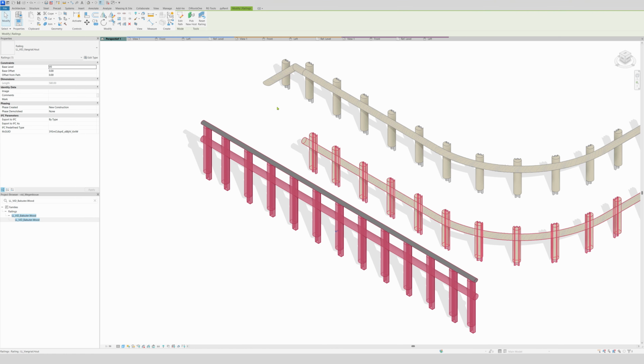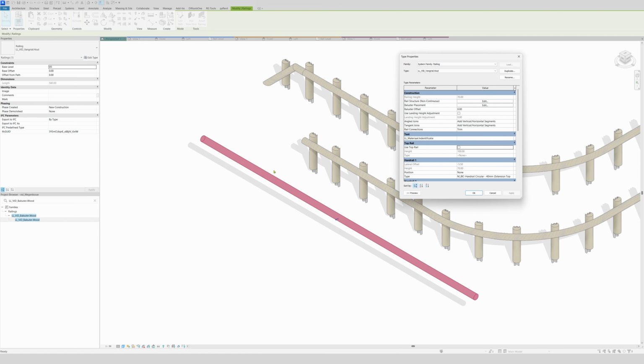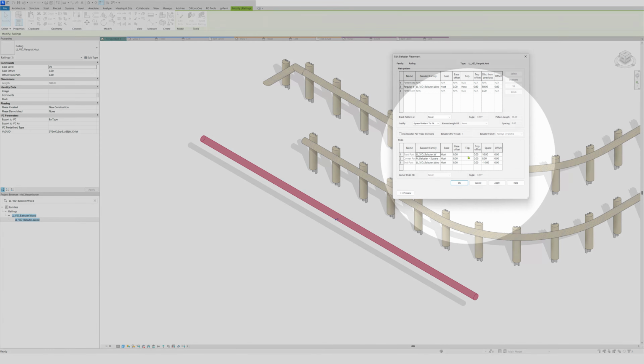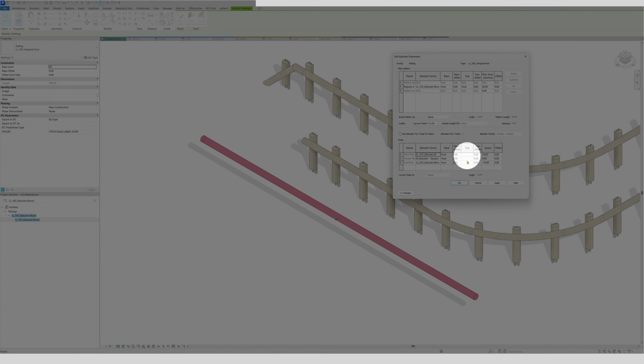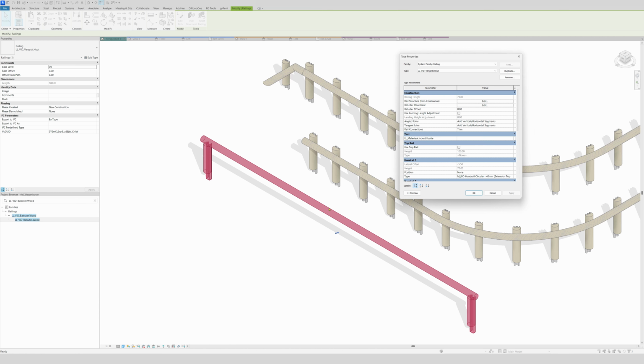Now we need to remove the top railing. I will do it the wrong way because I know how to do it, but I will use the wrong way. So I click apply. Okay, and now everything's gone. Don't panic because you need to host the balusters. So now the host is gone, so you don't see where it hosted. Then you just select the rail wood that we just made. Click apply. Okay, apply, and there they are back.